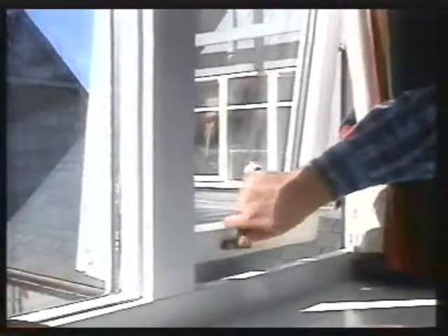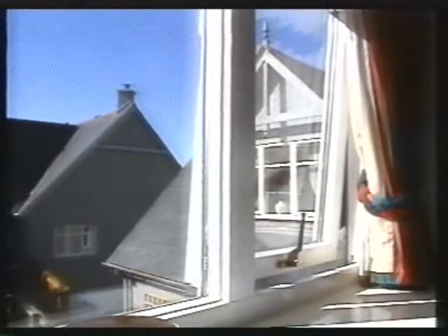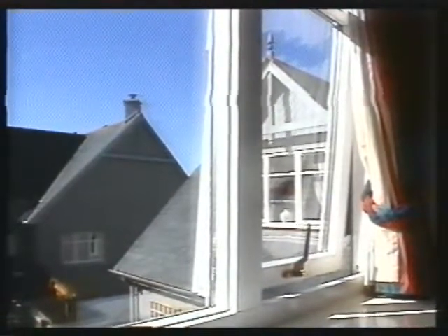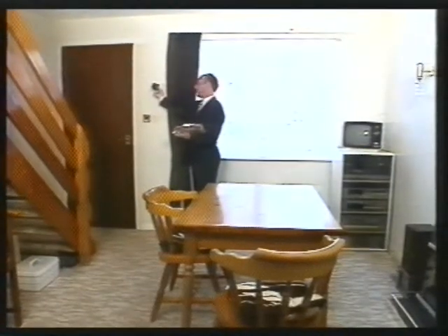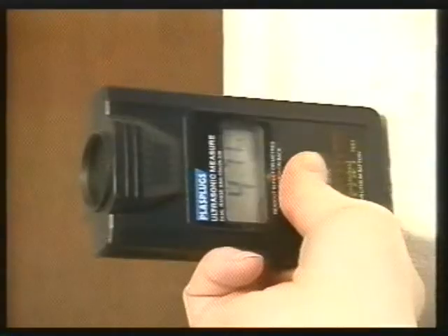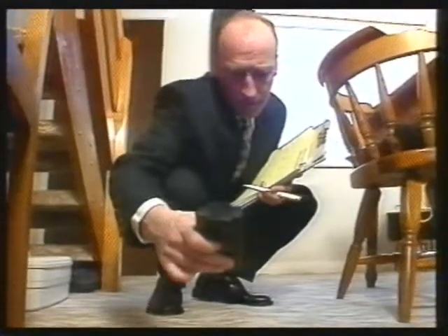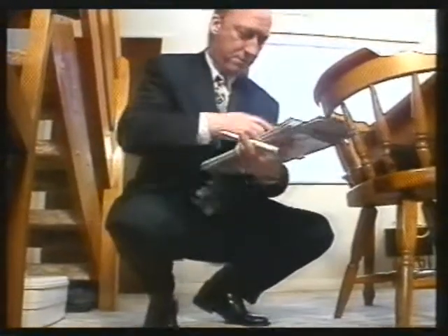The amount of heat lost through ventilation varies. Of course, we can't do without some ventilation, but we do need to know how much there is and what effect it's having. Heat loss this way is usually defined as the volume of ventilation air moving through the room each hour divided by the volume of the room itself. In other words, the number of air changes per hour.